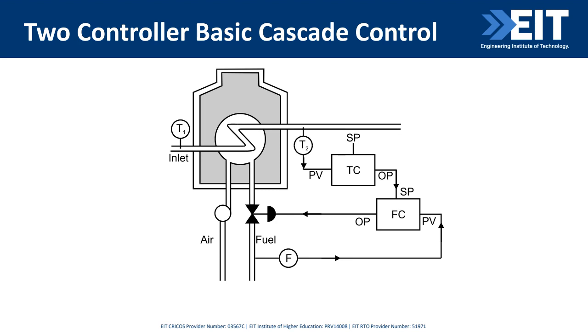We've taken the original loop, this one here, the primary loop, and we fed it into another cascade loop here. So the output from this loop feeds into that one there, and you're now controlling this loop here with a valve, which is fine, you've done that before.